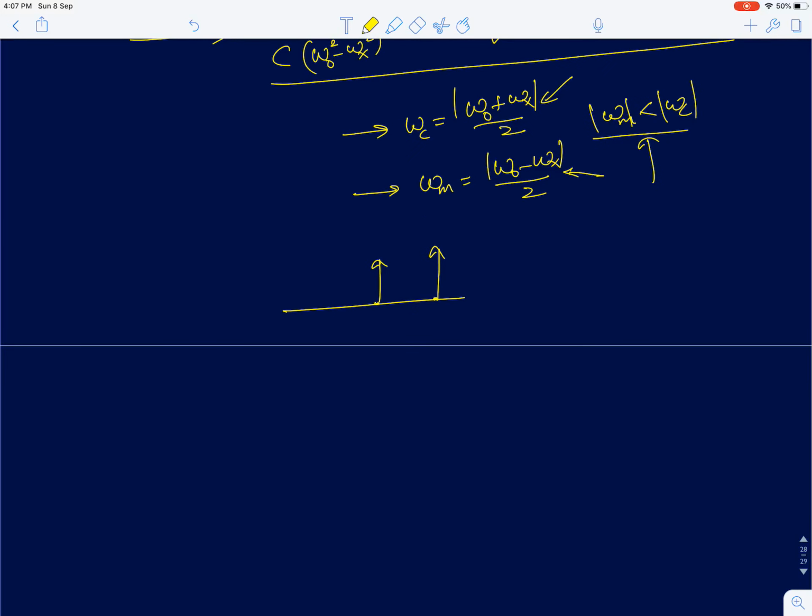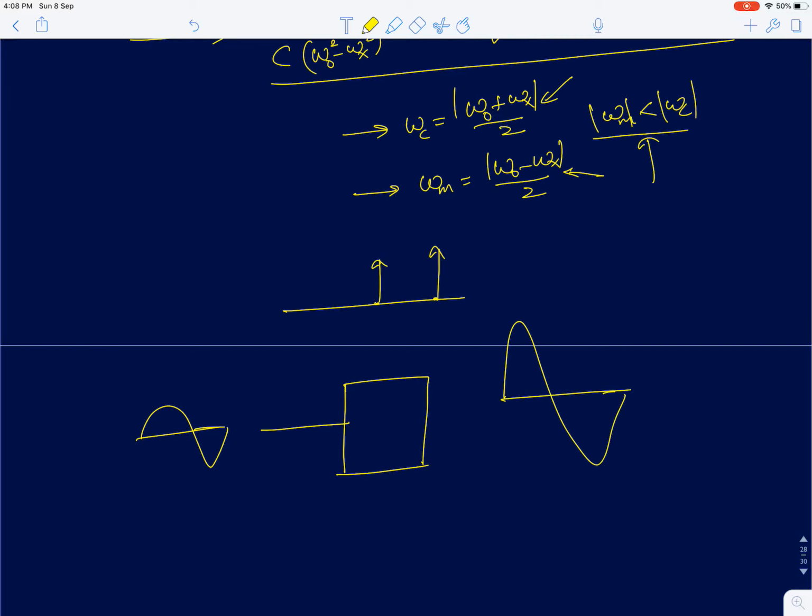Okay, and again that should sound intuitive, because in a resonant system, if I feed any sinusoid whose frequency matches with the resonant frequency of the system, the amplitude of the output sinusoid is obviously going to be much greater than the input. And since this is a lossless resonant system with an infinite gain at the resonant frequency, you should actually get an infinite gain in the steady state, and that's what happens in the first case.